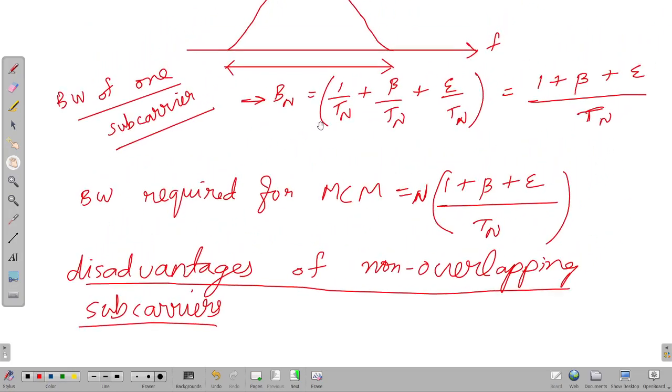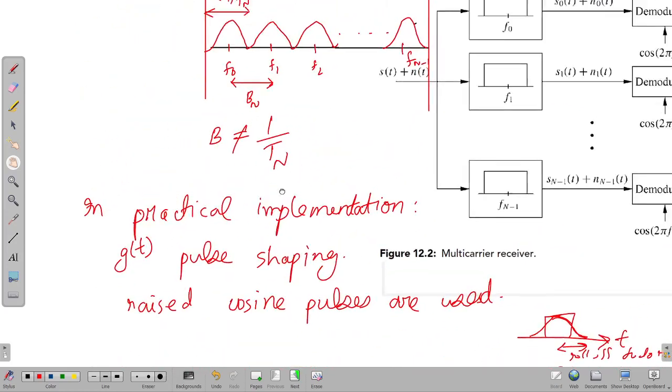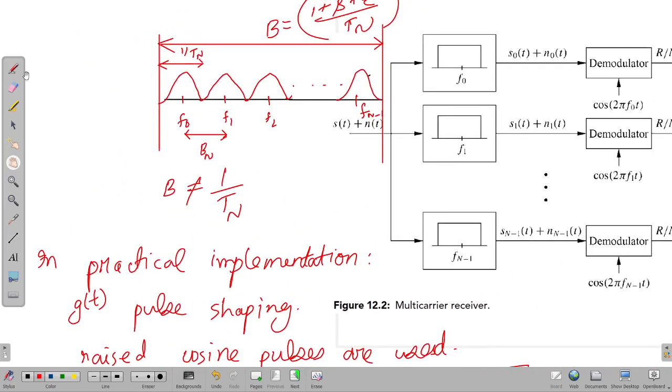One of the main disadvantages you can see here is that these subcarriers are band limited to Bn, and you need the receiver band pass filter, BPF, to have sharp edges, because you need to take in only this signal. You want only to have this signal.